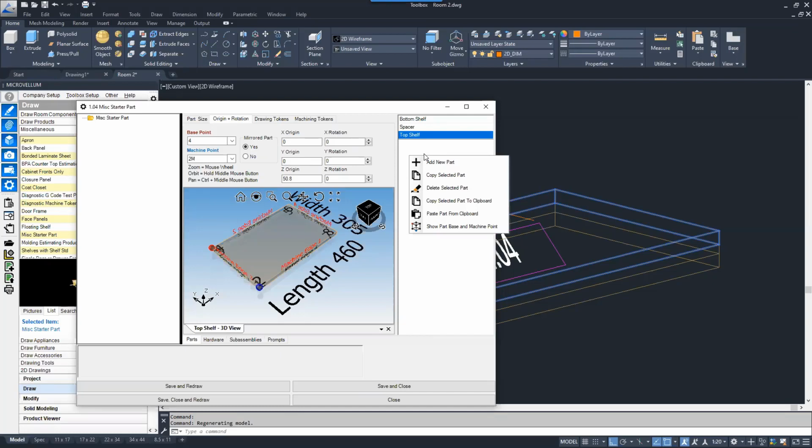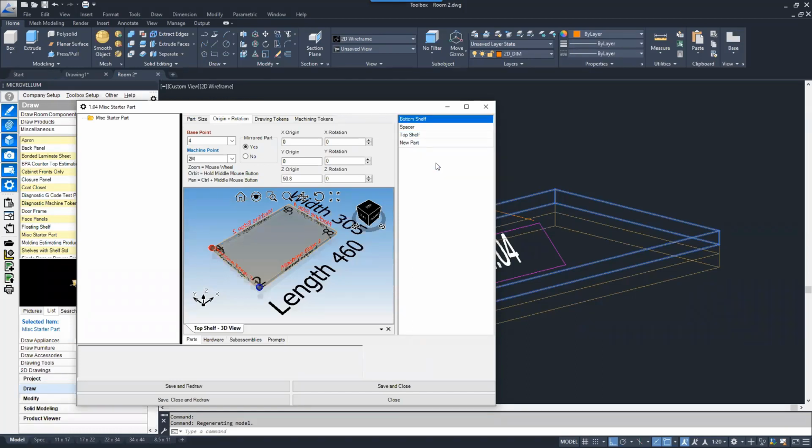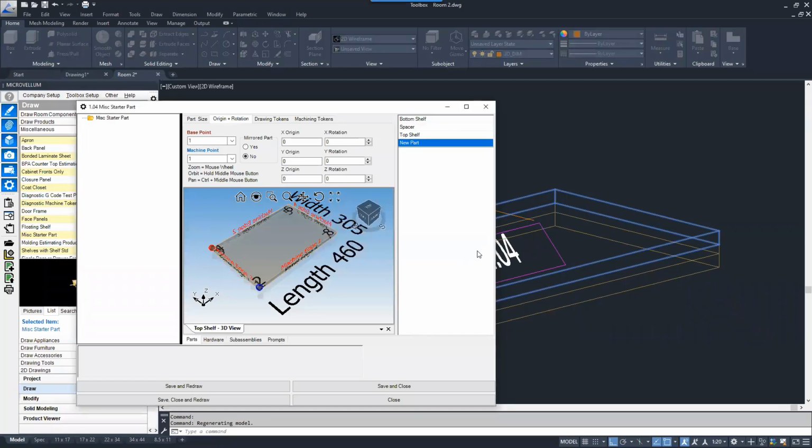We're going to use a dado token, and so we're going to create a part that is the LED strip and a part that is the hover bracket, and then add a dado token to each of those, and that's what's going to actually perform the machining inside of our top and bottom panels. That's the power of Microvellum, that there are lots of different ways that you can do things, and the associative machining really allows you to link those parts together and give you exactly what you need.